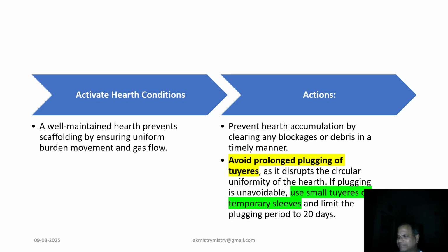Operate at standard stock line. Lower stock lines can lead to burden re-condensing and accretion formation. Ensuring proper stock levels are maintained helps stabilize the top temperature and prevent zinc condensation at the offtake. Finally, when you handle high alkali burden, do so carefully. Reduce slag basicity regularly to remove accumulated alkali metals. So remember, this also minimizes alkali damage to the burden and the lining.